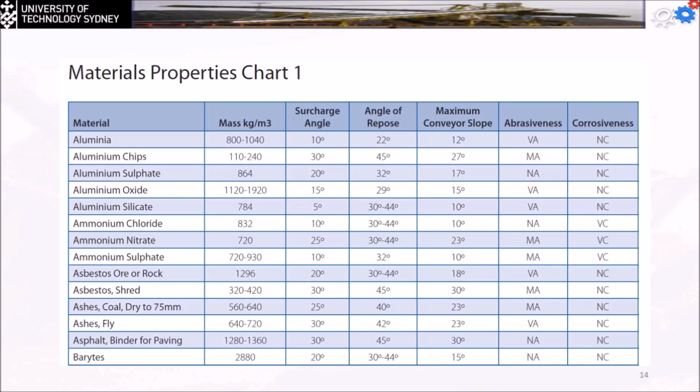If you have two bags, one of them was opened on a humid day and the other was sealed, then you bring both and check the angle of repose. The open bag is going to have a very high angle of repose. The other one is going to flatten. So it's all about humidity, the moisture content. We are going to check that, and it's actually going to be a very important factor in the design.